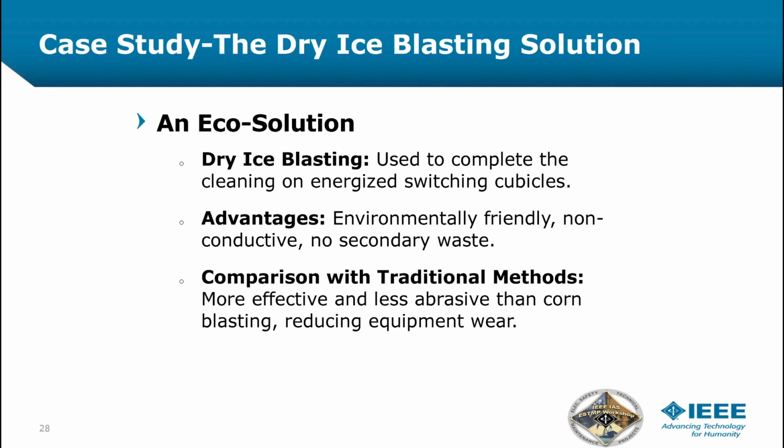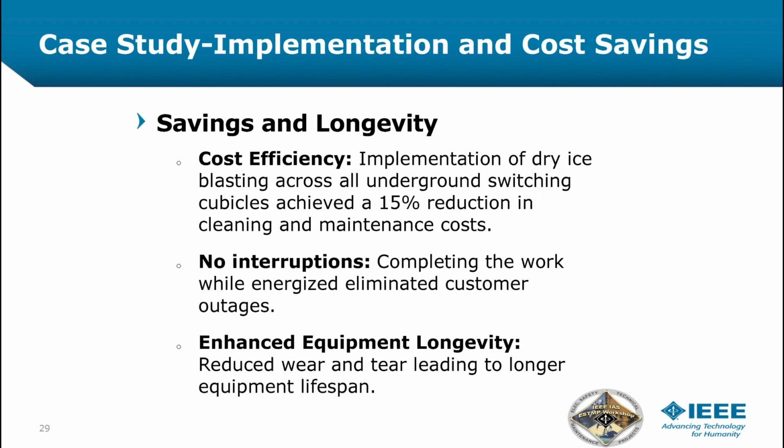An eco-solution, dry ice blasting used to complete the cleaning on energized switching cubicles. The advantage of environmentally friendly, it's non-conductive, there's no secondary waste to clean up. Comparison with traditional methods, more effective, it's less abrasive than corn blasting and reduces equipment wear. Savings and longevity, cost efficiency.